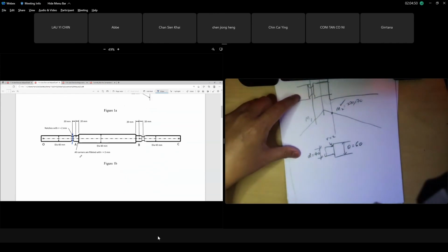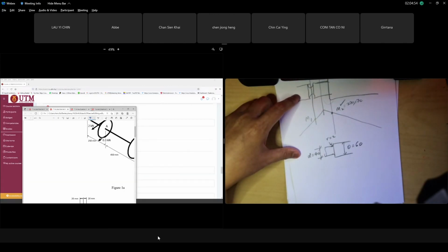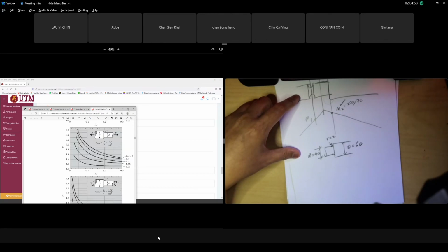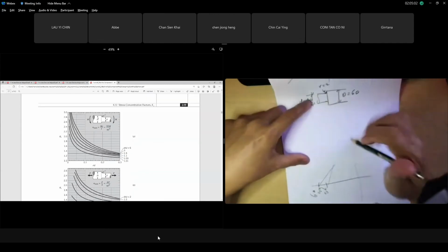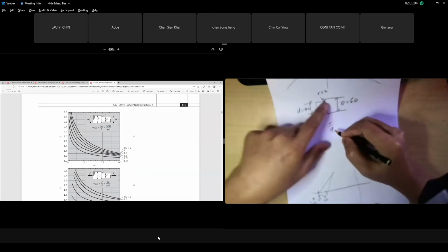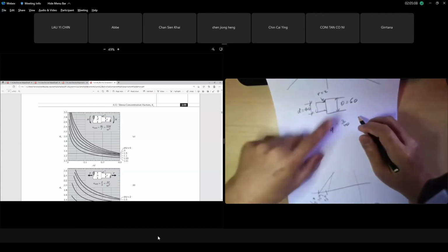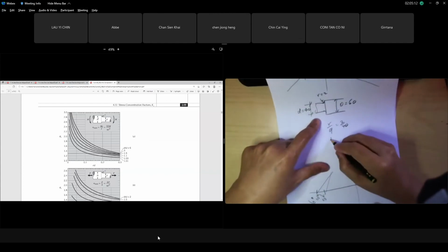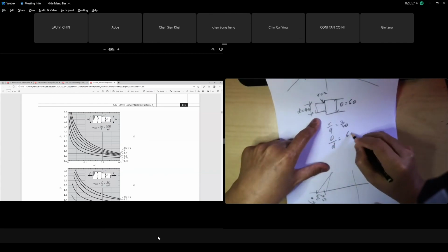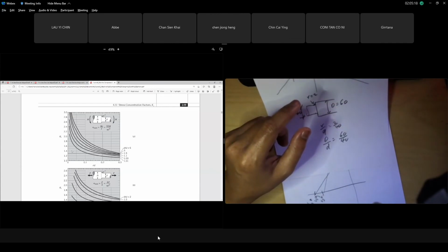So your approach is the same. So you use that in your textbook. In your textbook, you take the ratio r over d, D over d. This is for shoulder. Nampak? For shoulder. So if you look at my live video, you take r over d is 2 over 40. Just now it was 2 over 36 for the groove. This one is 2 over 40. And big D over d is 60 over 40. The same approach you use to get it for your bending.